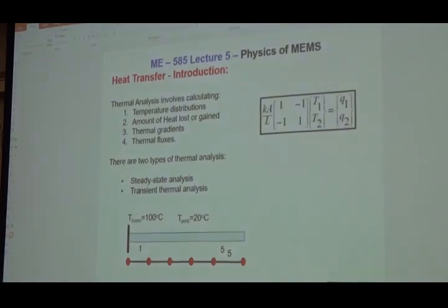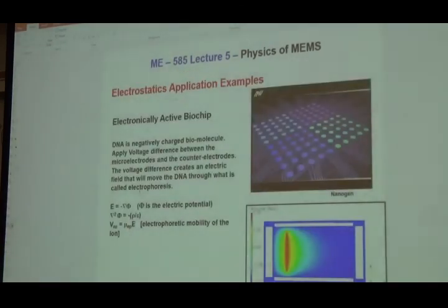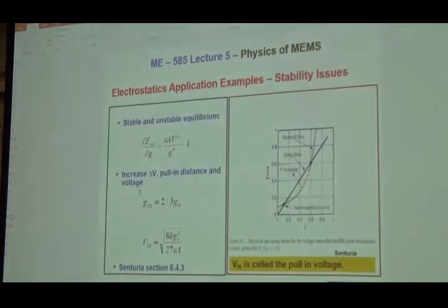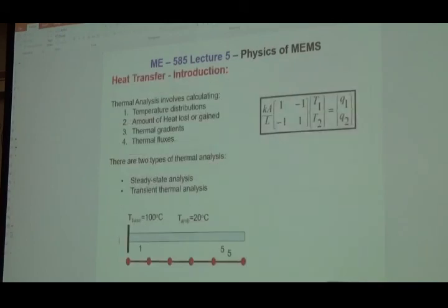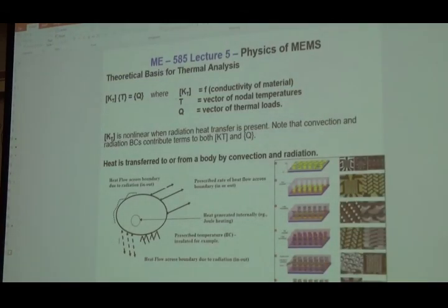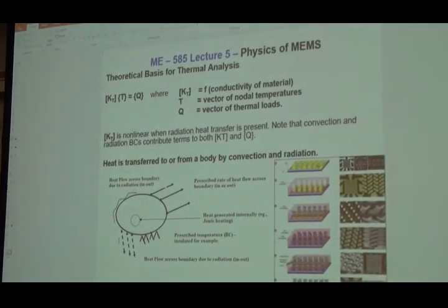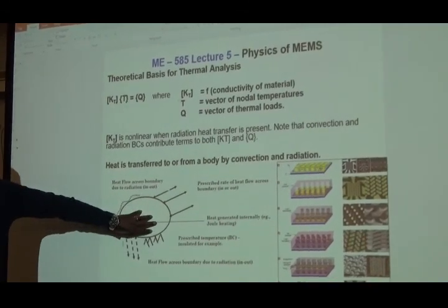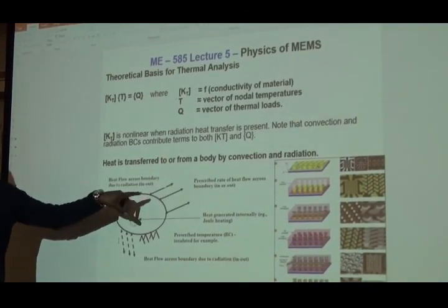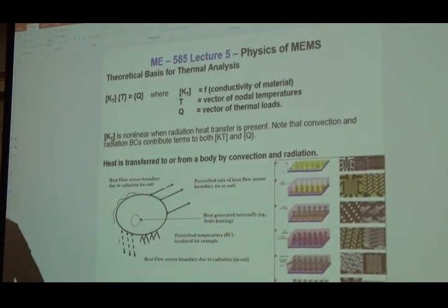Okay, so heat transfer. Essentially, I was going to derive the same thing here. So all I need you to know again from that is you could solve del squared T is equal to 0, and you could solve the conduction problem. So in general, a thermal problem is not only conduction. That's convection, right? And then radiation. But if I'm just interested in the conductive part, then I solve del squared T is equal to 0. The convective term will have a velocity u term times gradient of T. And then the radiation, if you want, you could apply it as a boundary condition.